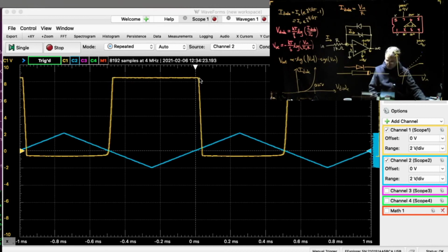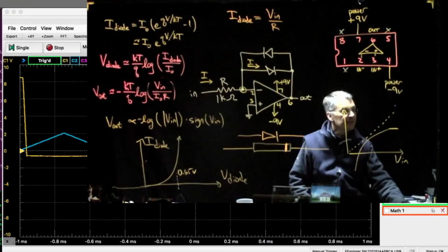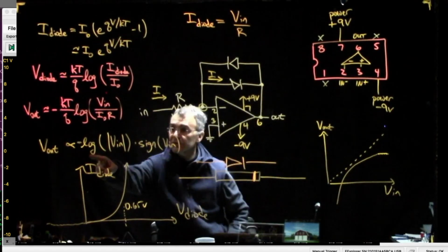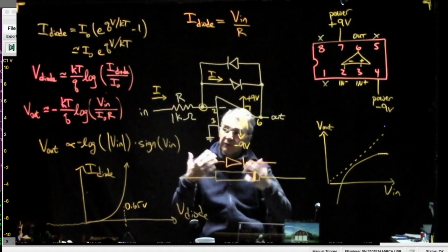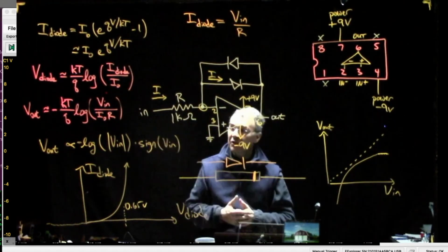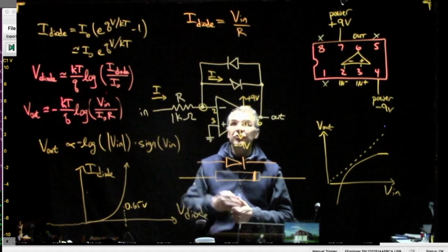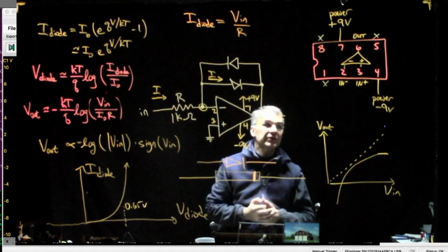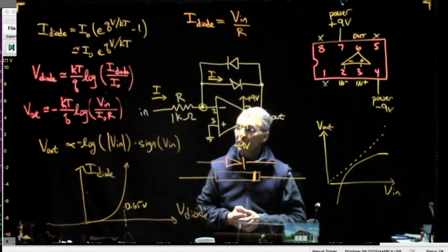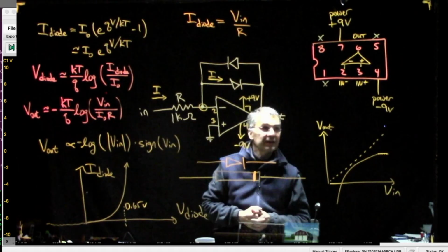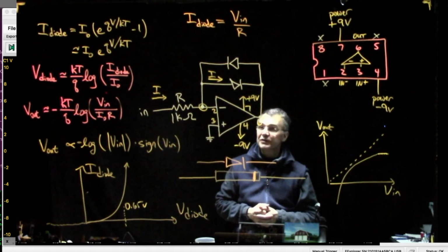All right. So anyway, I think the neat thing about this circuit is that again, you can make an output which is proportional to the logarithm of the input. And so then we know how to make an adder, and we know how to take a logarithm. And how would you take an anti-logarithm? I guess if you put the diode here instead of here, you could take an anti-logarithm. So if you have logarithms and then addition and then anti-logarithms, you could imagine making a multiplication circuit. That's kind of a fun potential application.